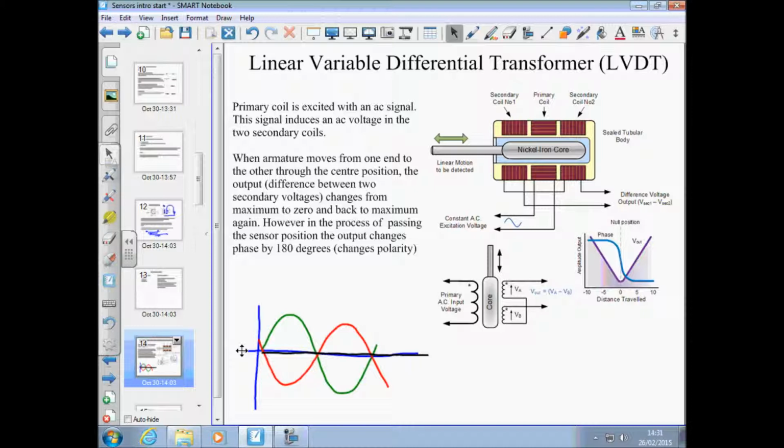you get an output. And they work it so the actual output is a sine wave, but you get a linear portion either side, or a close to linear portion either side, that they use for the effective output of this system. The output is an AC waveform, an AC sine wave, that they then rectify into a plus or minus DC signal.